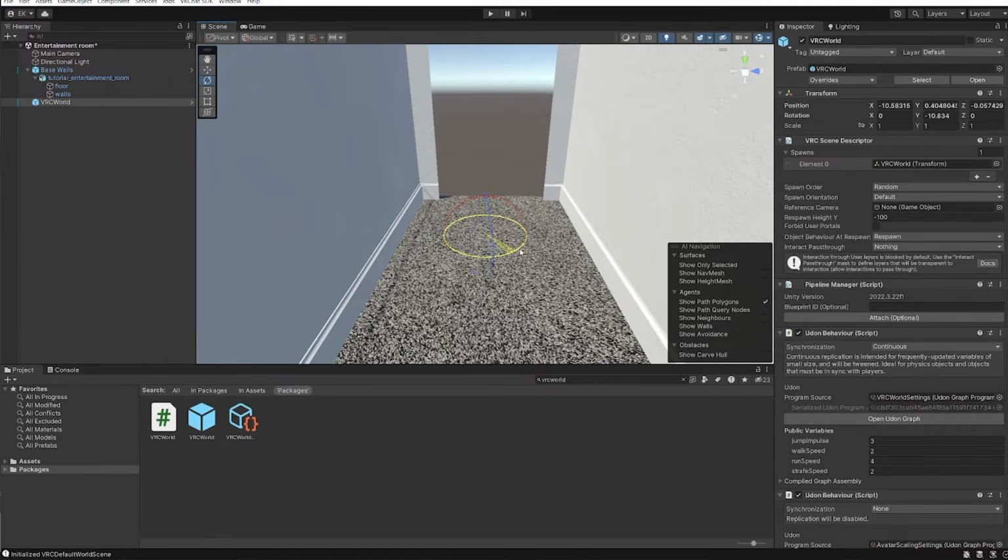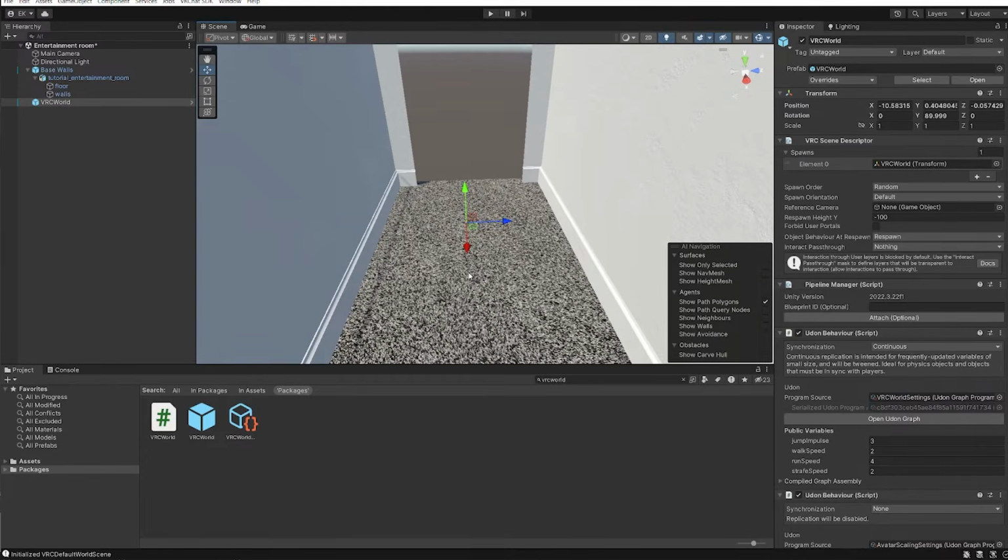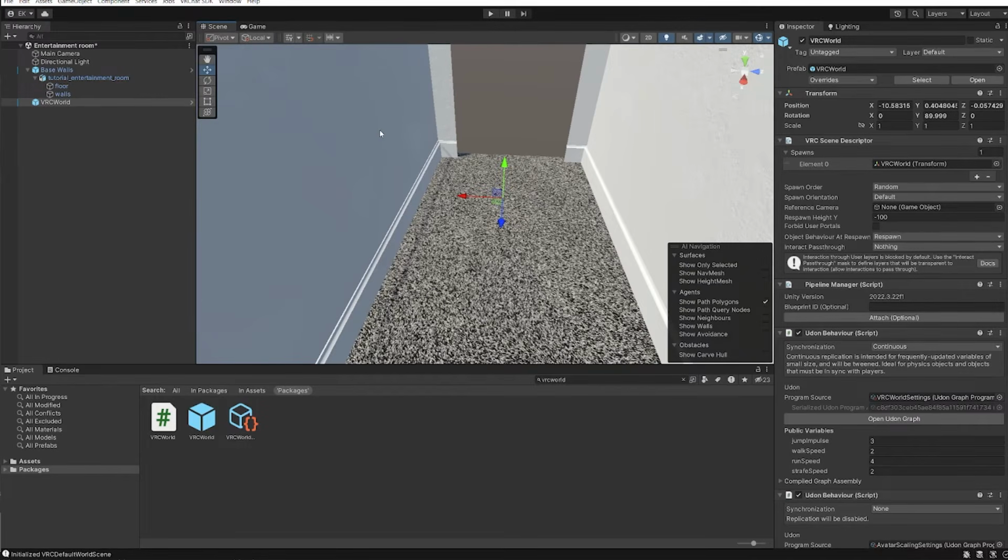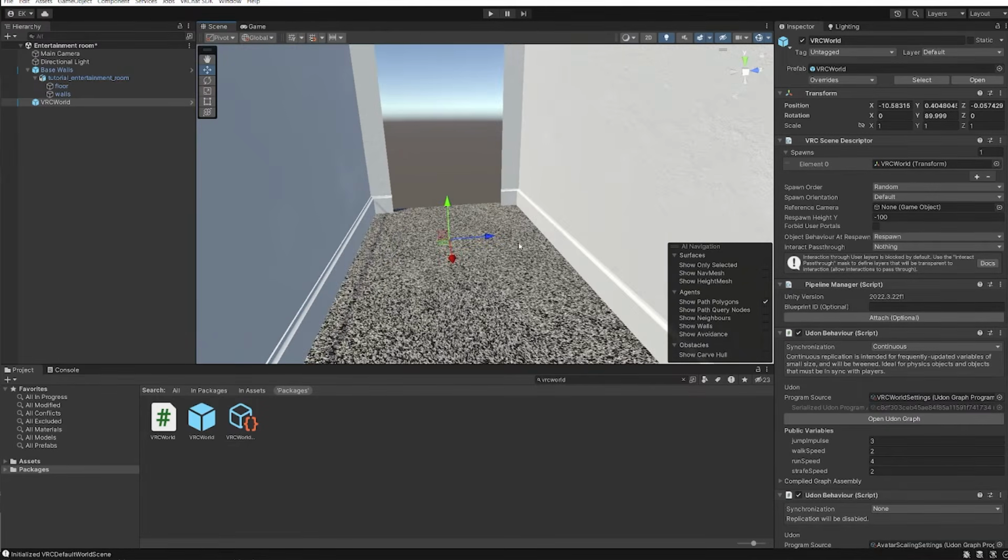We can grab the yellow to rotate in the Y axis, press Control to lock it, and we're going to rotate it 90 degrees. And now if we press W, which is the hotkey for the arrows, this blue should be pointed in this direction. The reason why it's not is because we have the global transform orientation selected. If we press local, it will show which direction the object is pointed. Global shows the direction of the scene, or like the world.